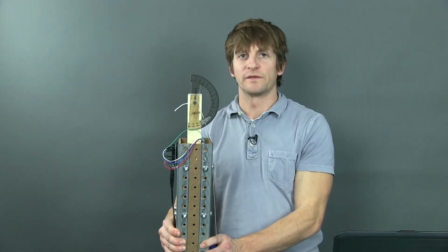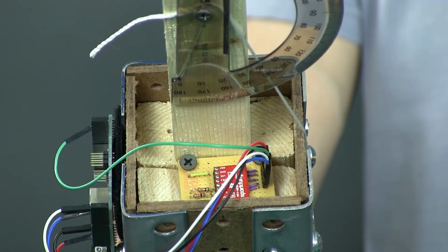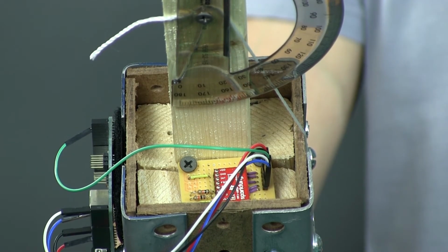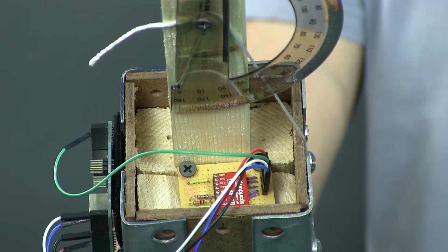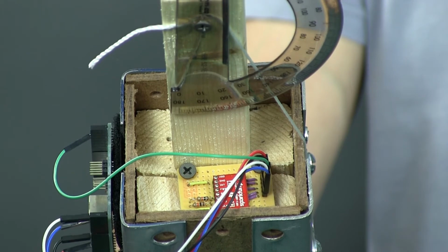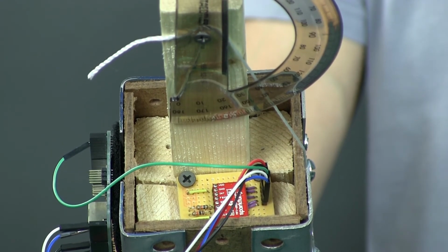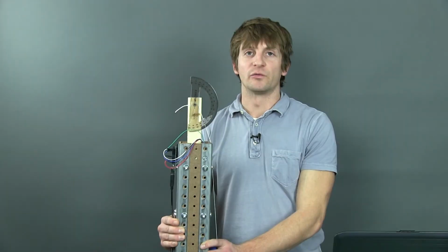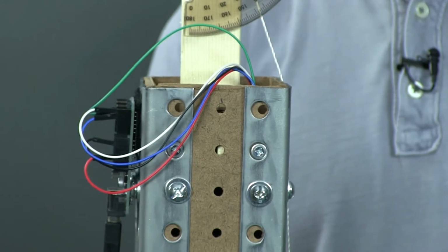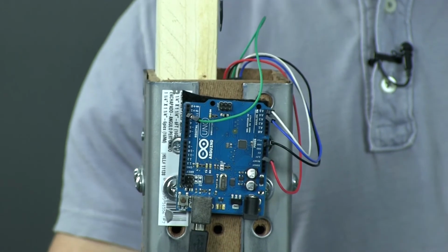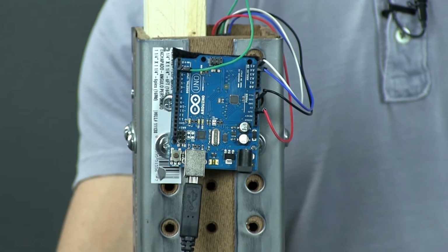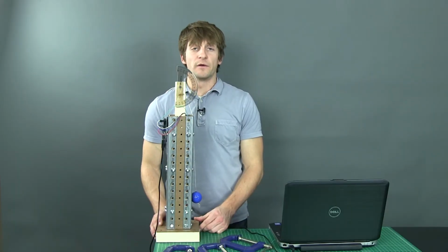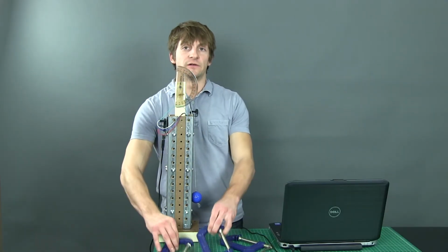The oscillations are measured with sensors that are attached to the top of the building. There are 6 sensors in total, 3 accelerometers, which measure rates of acceleration from 3 perpendicular axes, and 3 gyroscopes, which measure rates of rotation about these axes. The output of these sensors will provide us with all the information that we need to determine how the building is oscillating. This information is passed to a microcontroller, and this microcontroller communicates with a PC via a USB cable. Finally, the building is clamped to the table using standard C-clamps.